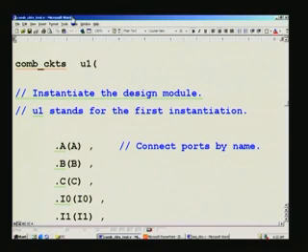Before that, let us see why we should declare that output as a wire, right. See, I pointed out that like this we can have a number of modules in the same test bench, or even within a design you can call any other design sub modules. In which case there must be a way to identify the connection between one module and the other. So, how do you identify? If you look at the circuit which you have hooked up in earlier days, you physically connect one particular pin to another, it may be from one IC terminating on another IC.